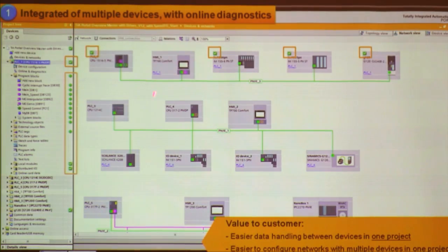And in this particular view here, this is an online snapshot of this particular PLC that I'm online with, and we give you diagnostics information. This is why you use this editor, and we're going to do it in a minute, to rapidly configure and add devices in. When you go online, it's not just a dead static display. This comes alive with diagnostics information that you can double-click and it'll bring you to more information for that.